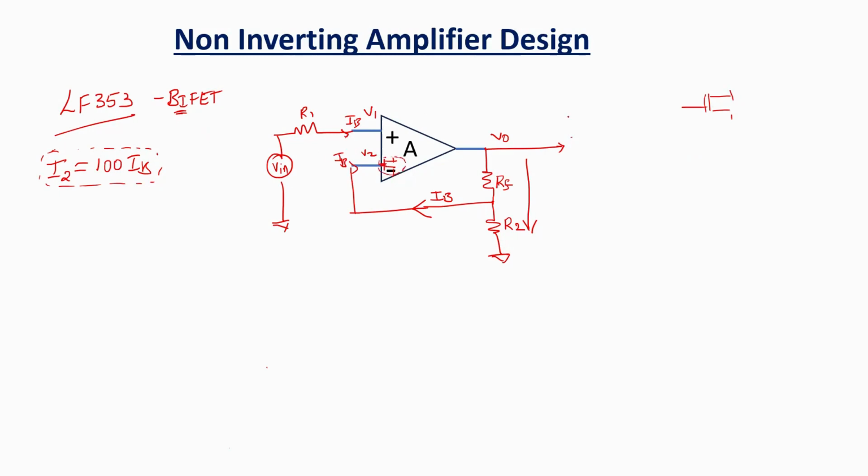Now what happens here is that although the current is pretty small, because of the large biasing resistors there is a charge accumulation at the gate terminals of the MOSFET. It takes a lot of time to discharge as well. So this causes uncertainty in the biasing of the op-amp.